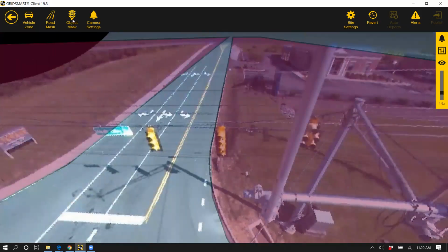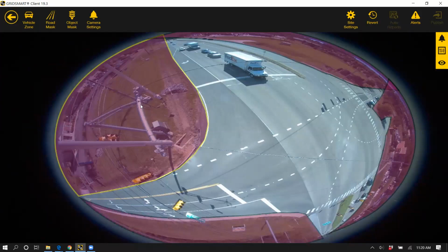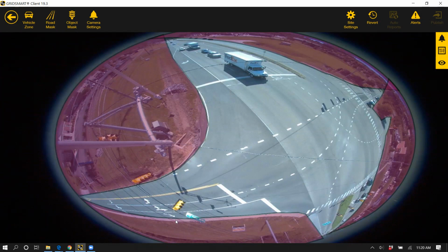So an object mask is an obstruction between the camera, where the position of the camera is up here, mounted off of this strand pole with a luminaire arm. It looks like there's an additional bracket here, and then we're going straight up with the riser off of that bracket. So from the position of the camera, an obstruction is anything that's blocking our field of view to the roadway. So these road signs here, the signal heads,